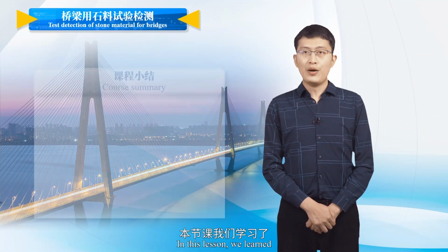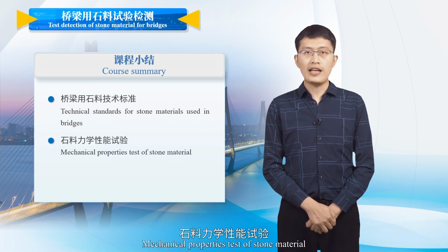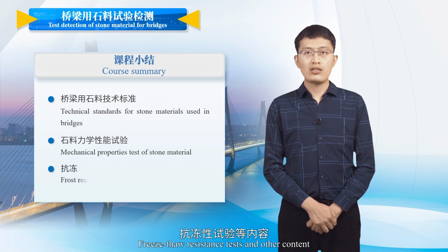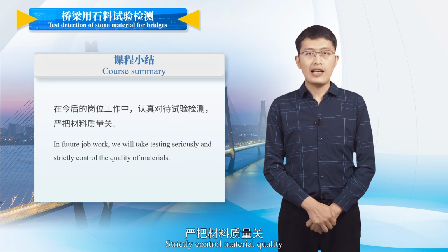In this lesson, we learned technical standards for stone materials used in bridges, mechanical properties test of stone material, freeze-thaw resistance tests and other content. Hope that in your future work you take test detection seriously and strictly control material quality.